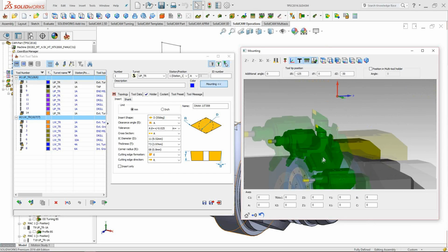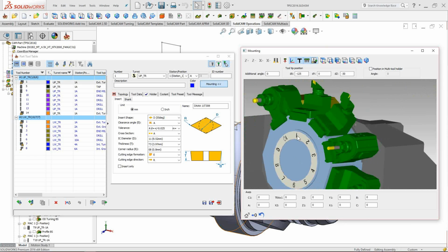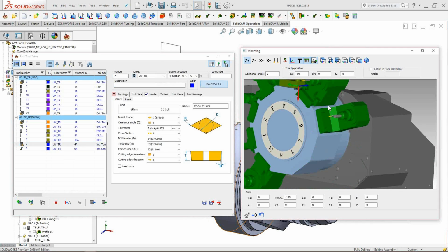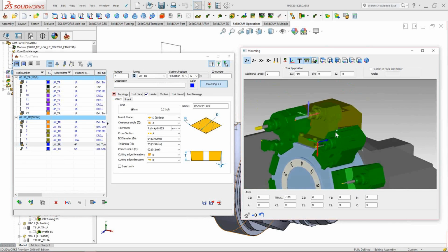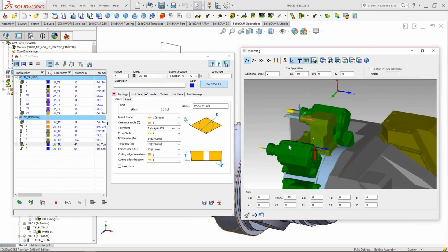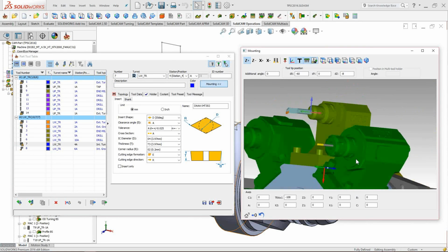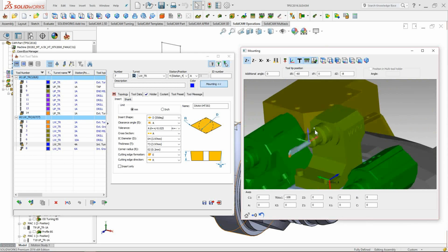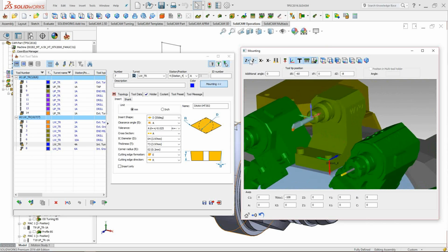And pay attention, here I have my active tool number 1. Let's take a look, for example, and I would like to load tool number 4. What I need to do is simply click on the particular tool itself. So it's on station number 4. Just click it, and the machine preview will automatically bring you to this third position. So that's very nice. And besides that, here we have the station position, and here we have the tool mounting position. It's clearly displayed here, and I'll talk now more about those tools.